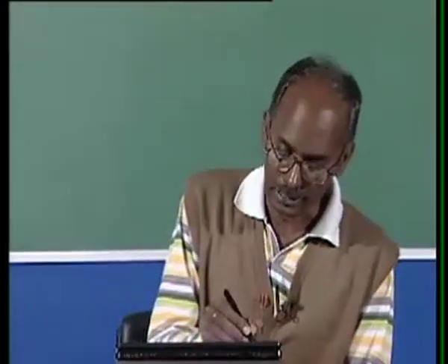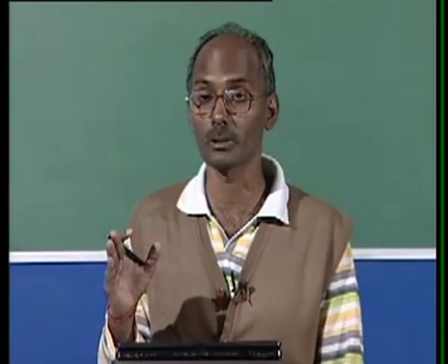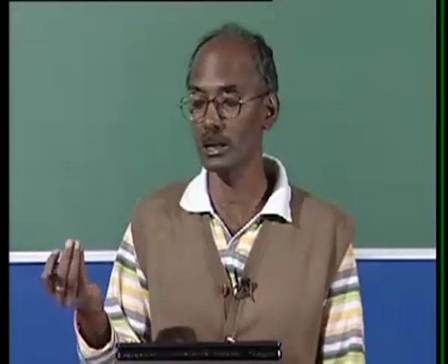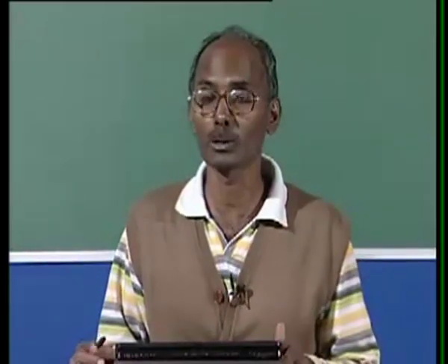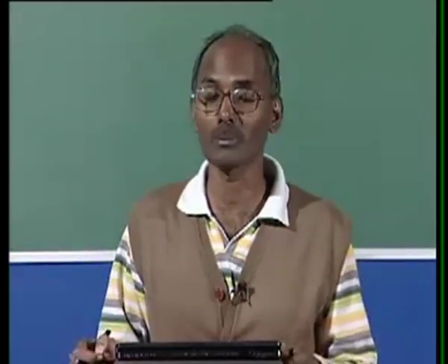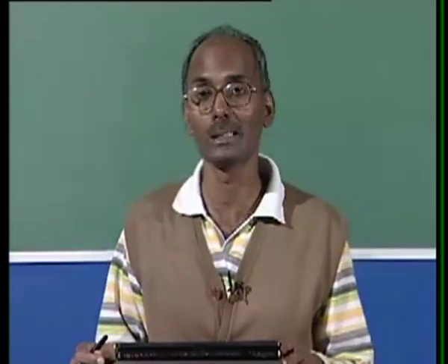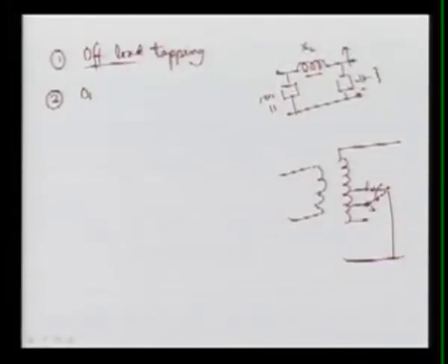Another transformer here: since it is not always possible to de-energize the transformer and then change the tapping, because that will create another problem as your supply will be interrupted. If your transformers are small, then we can go for interrupting a small load. But if we are talking about big power transformers, interconnecting transformers, ICTs connecting 400 by 220 kV lines, it is not possible to de-energize and then change the tapping. So for that, normally we have the online tap changing positions.